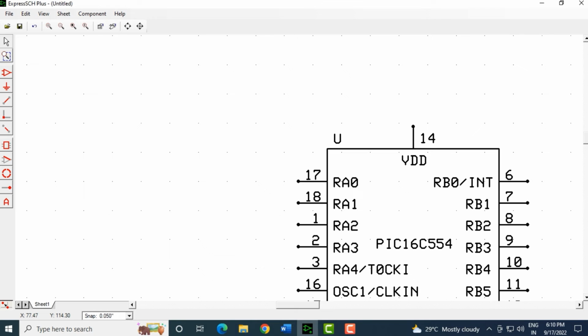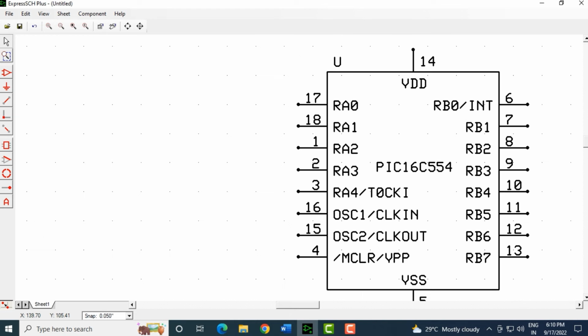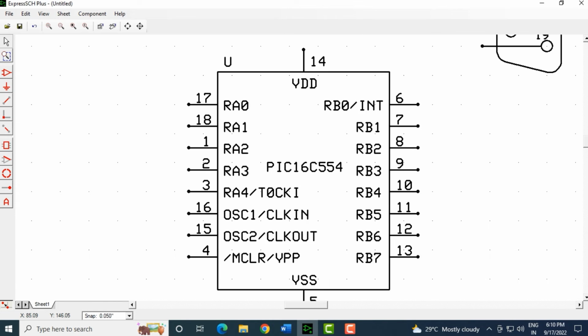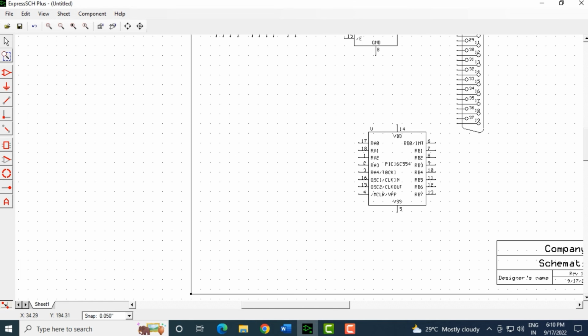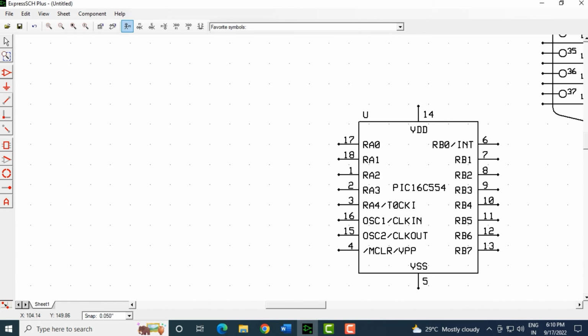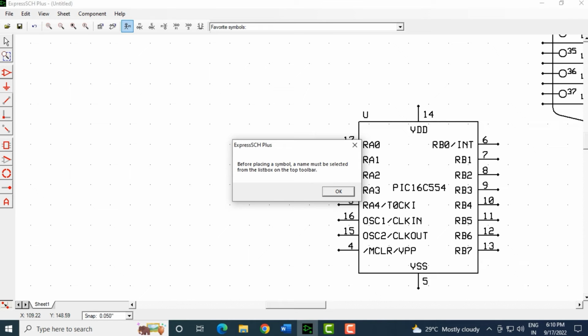If you want to zoom in, click on that, zoom in. Move the side scroll or the bottom scroll, left and right, and you can see what are the different pins and what are the data buses or control buses provided. And then you have the placing a symbol or signal label. So let's select this, and I'm placing a single symbol here.